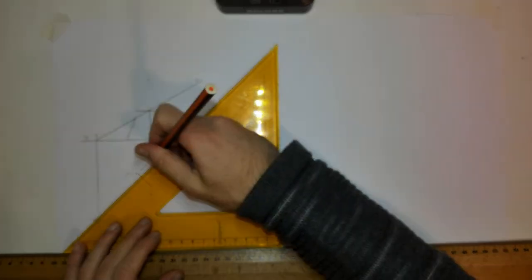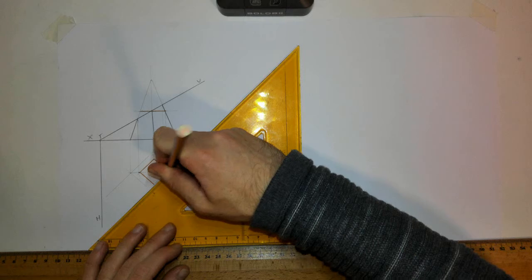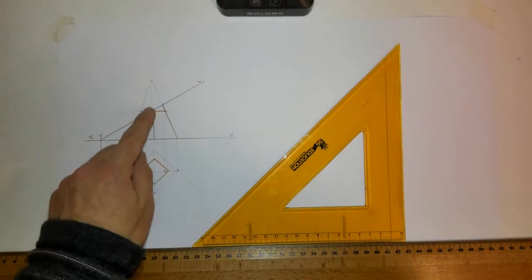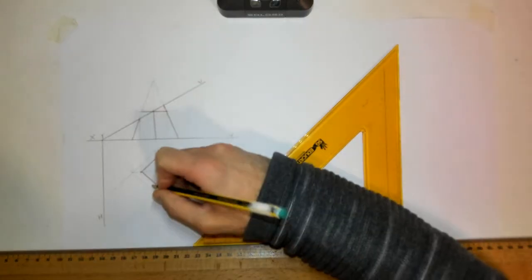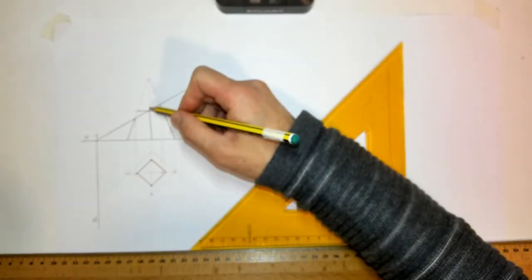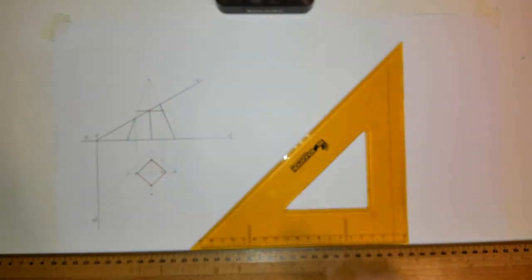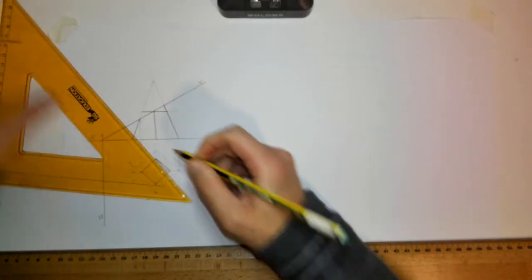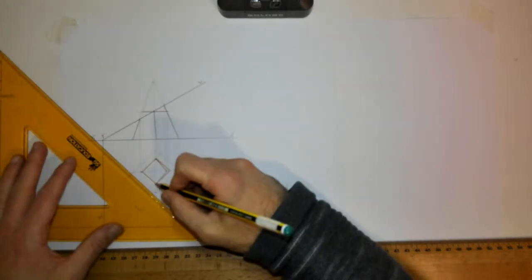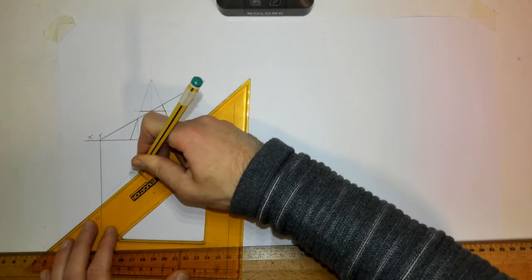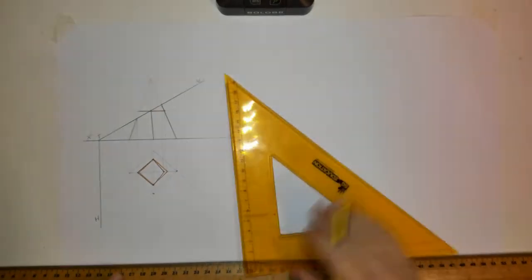Remember, a horizontal cut at all times is going to produce a square in this solution. And depending on how far down we go or up we go, it depends on the size of the actual square. And what that gives us is this point and this point, because they lie along those lines there. So what we can then do is connect those together, and that gives us the plan view of our actual cut then as a result. So our cut surface is that there.